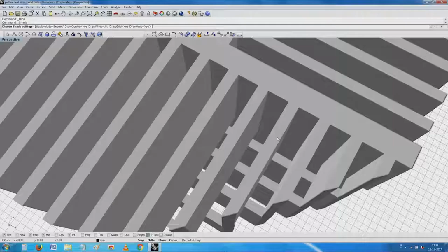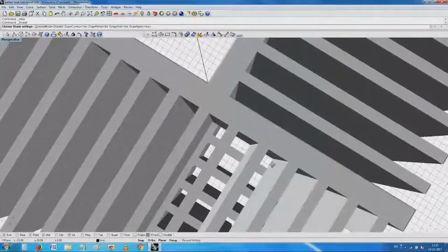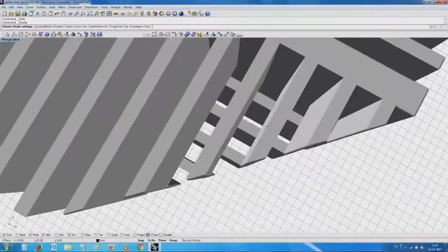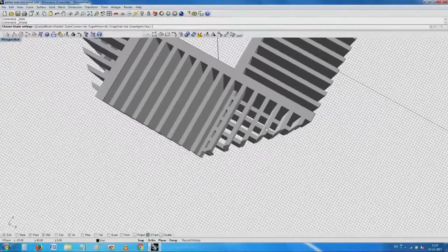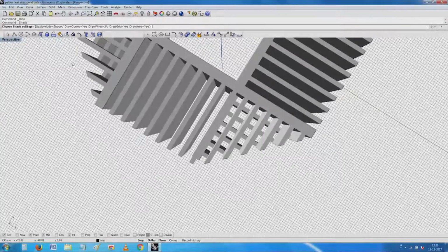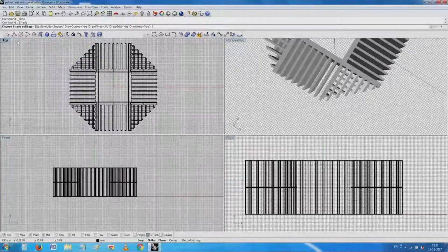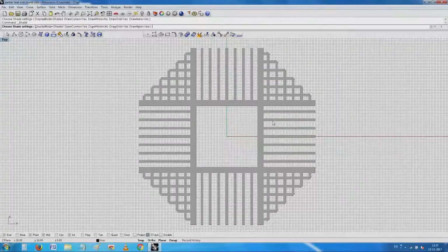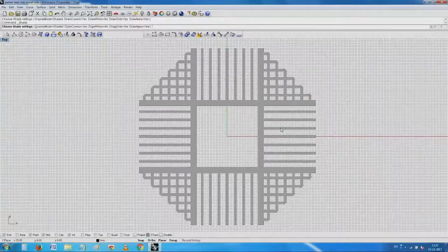If I had control on the profile extrusion, probably I will also ensure that at this point the spacing is a little larger. You understand, no? The spacing is a little larger, to the extent that when we look down on this area here, you will have less interference from adjoining heat sinks, and then I have what looks like a neat rangoli.